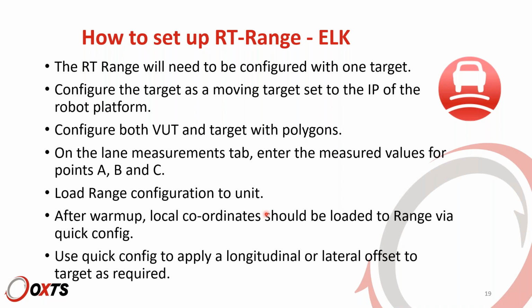So rather than north and east, you define an origin point, you define an axis, and you can then have forward and lateral of that origin in that particular axis. It's more useful generally for AEB tests, which always require this. Generally for lane departure warning, it's simply the distance to the lane line that matters, so you don't often need to do this, but for emergency lane keeping, it will be a requirement.